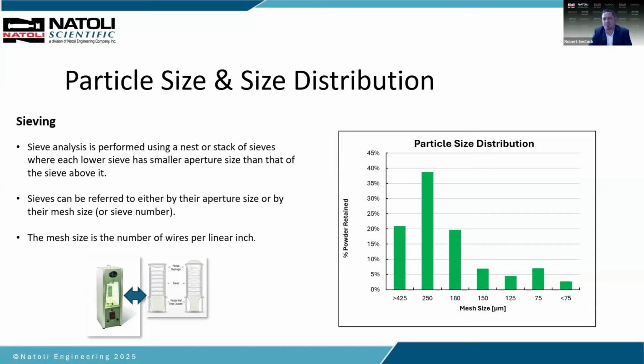Why is that important to us? Well, if we know the compressed density, which is the mass, the weight over the volume of that compressed tablet, that divided by true density gives a solid fraction. A solid fraction of 1 means we compressed that tablet where there's zero porosity. There's no more air. We squeezed out all the air. Now the tablet density equals the true density. That's a solid fraction of 1, and porosity is 1 minus the solid fraction, so that would be a porosity of 0. I've never made a tablet or seen a tablet at a solid fraction of 1. I see the tablet will actually destroy itself and cap and delaminate before it gets there, because there's no room for those particles to rearrange and move.